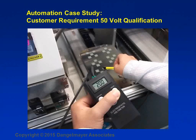So they wanted 50-volt certification of the process. Here in this particular stage, we found that the devices were charged to 200 volts, which violates the customer requirement at face value, or as it might appear.